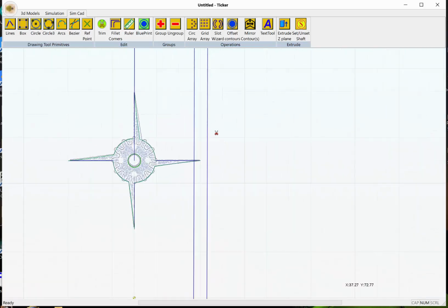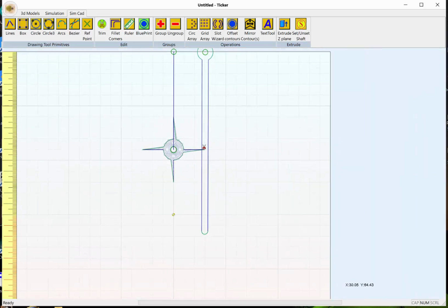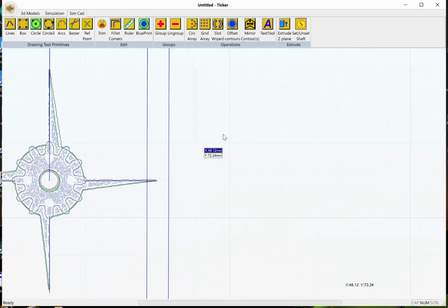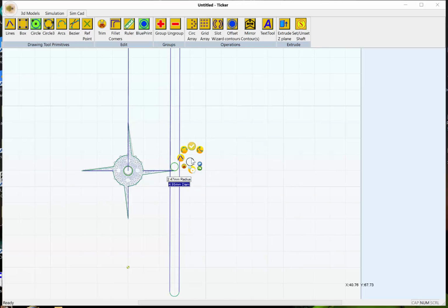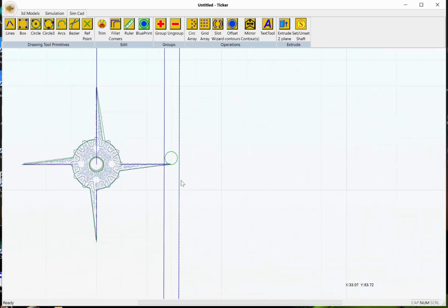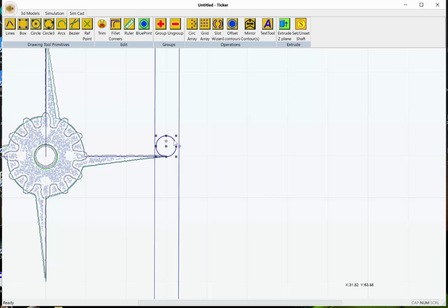Now on top of that object, we're going to want to put a shaft as a trigger, which holds that pallet still. So I'm going to just put a pin here, and since I like to use 5mm shafts, let's put it at 5mm. You'll notice that's not very well centered, so I'll cancel this operation.